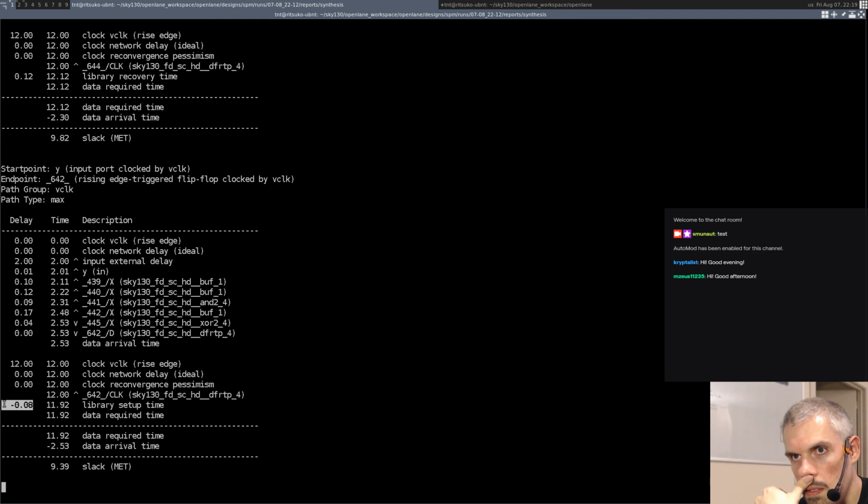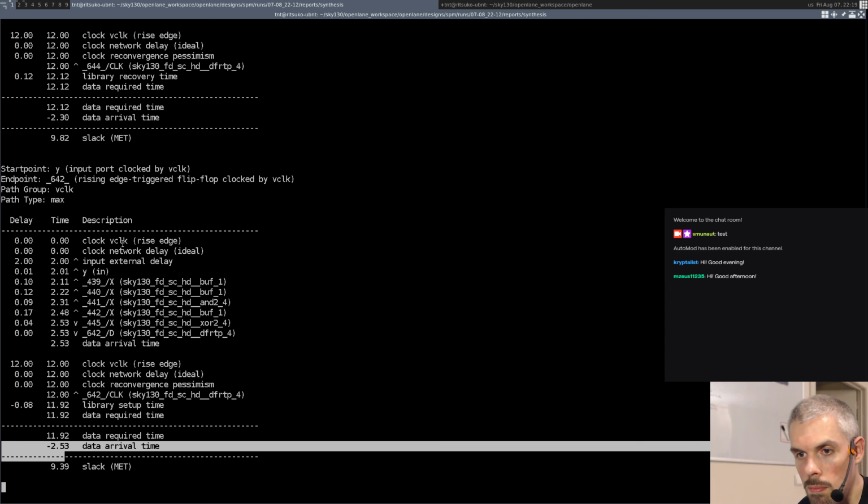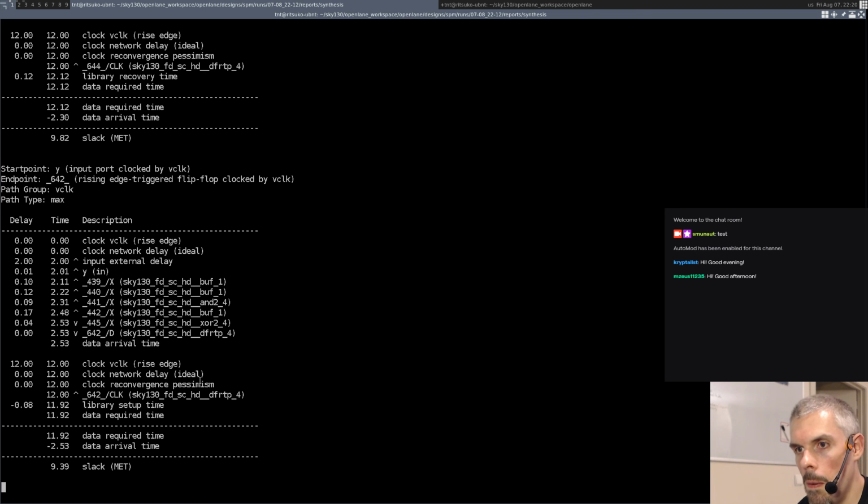That's interesting. So the fact that the hold time and the setup time are negative is a bit surprising. I mean, there is a gap between the two of 0.02, but that means there is only a gap of like 20 picoseconds between the hold time requirement and the setup time requirement. The required data valid window is super small, which is interesting. Anyway, we meet the timing by a massively huge margin, right? So there is no trouble there.